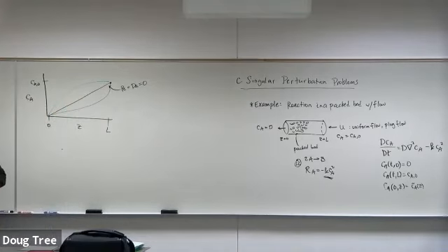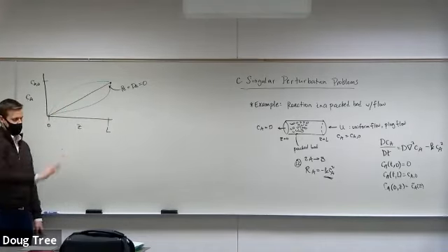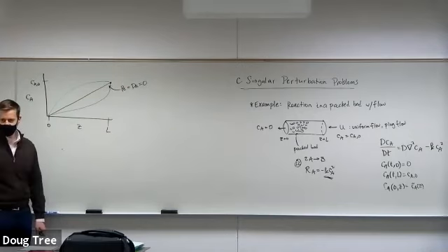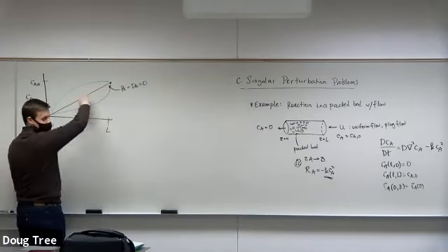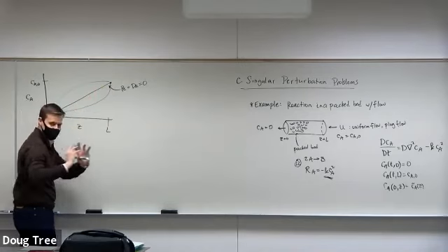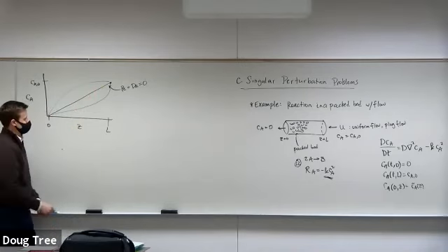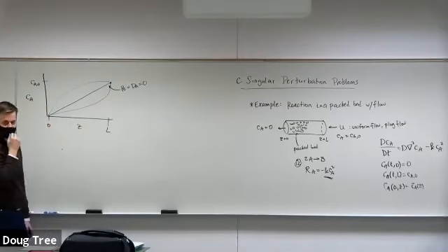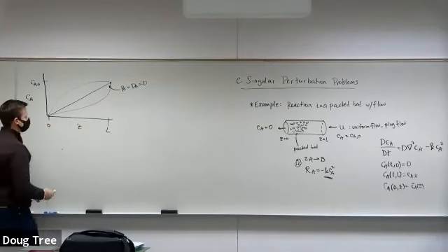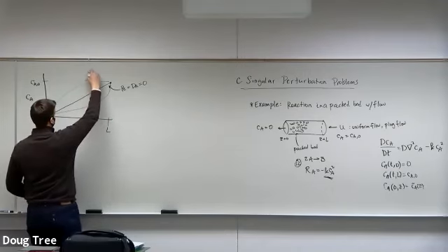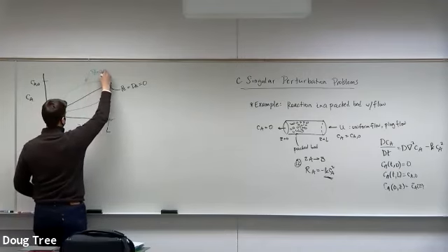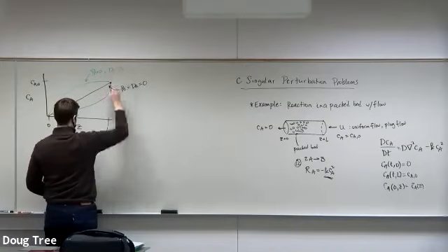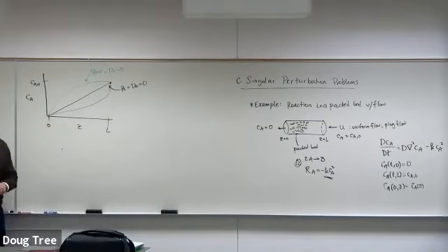Does that make sense? There's some kind of momentum pushing that in. There's diffusion here, but there's extra convection that's carrying it from the side where it's high concentration into the system. So this is the case here where Peclet is greater than 0, but the Damköhler number is 0.